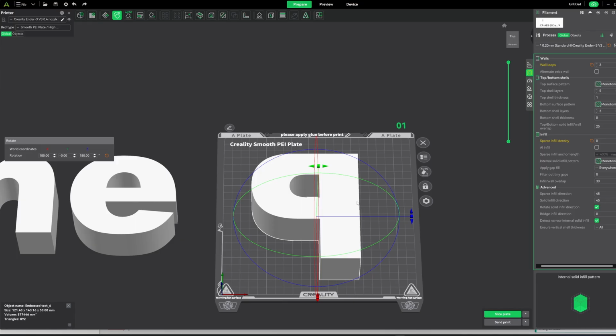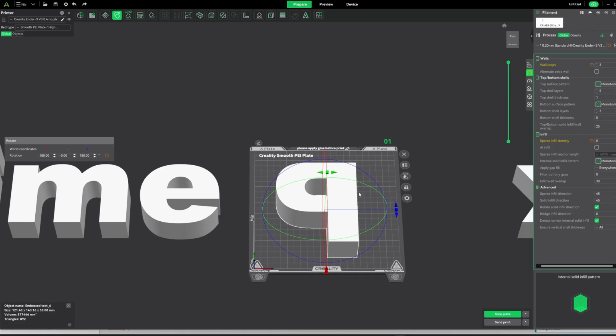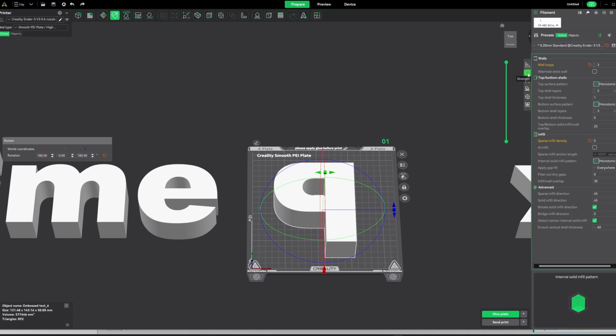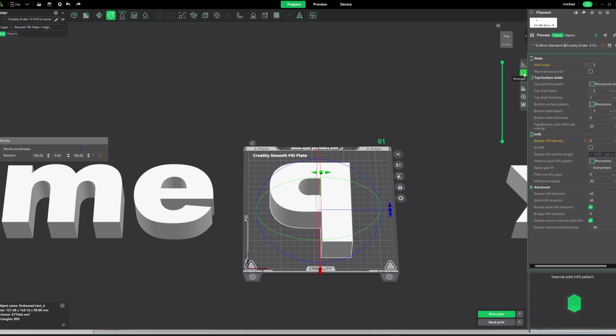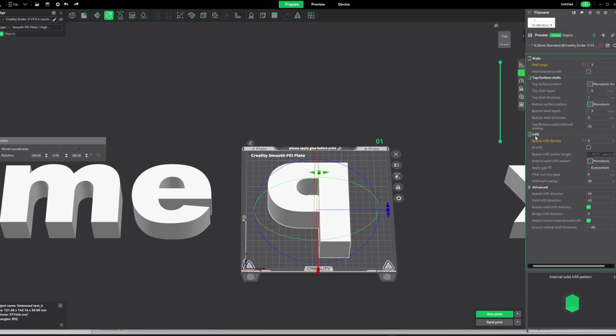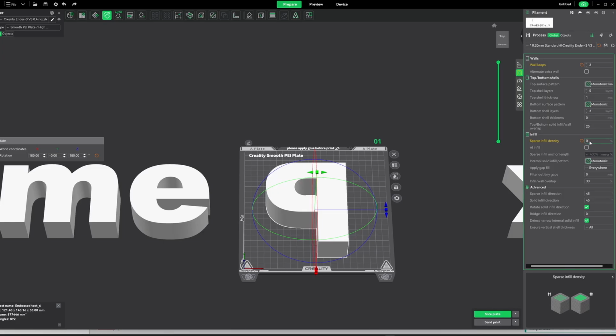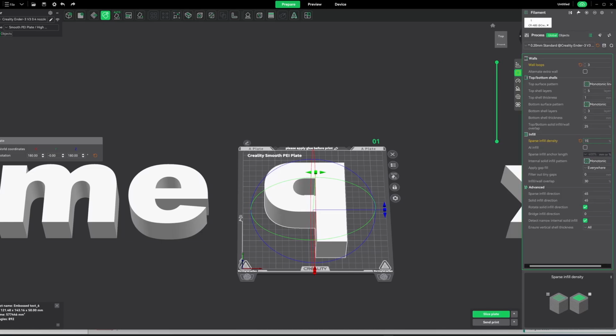That's another trick. And as I've shown you earlier, I like to create trays or bowls because I like to save weight. I like to glue these letters to a wall so I don't need any infill. And it's also super easy to change. In the right menu you can find the strength menu, or maybe it's called differently in your slicer, but somewhere in these menus you will find the infill, and by default it has a setting of around 15 to 20%.